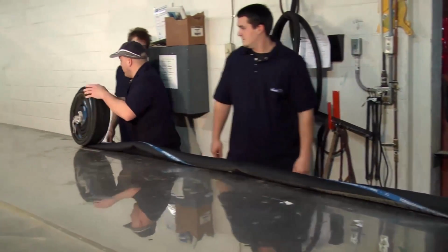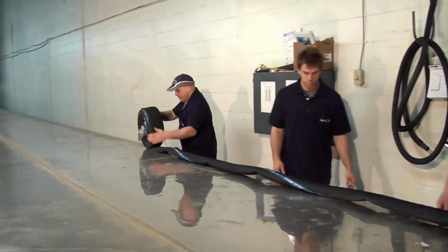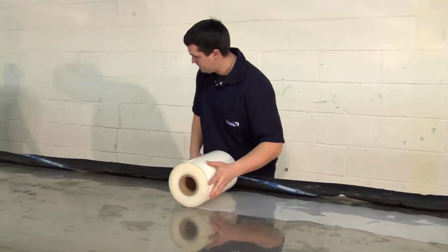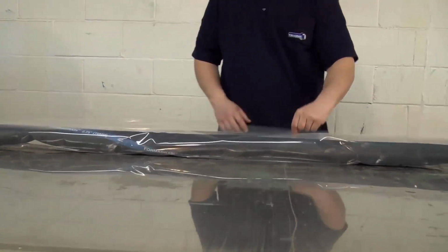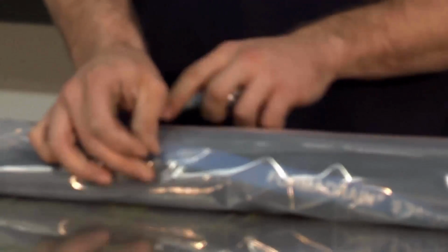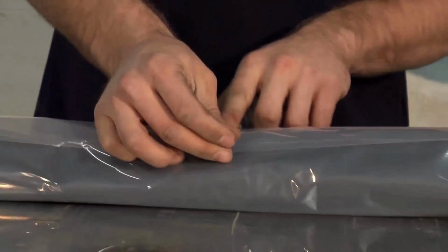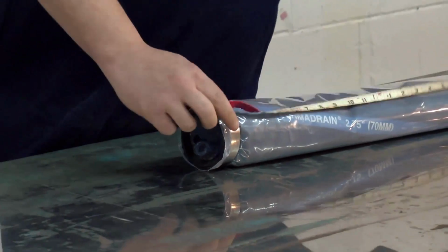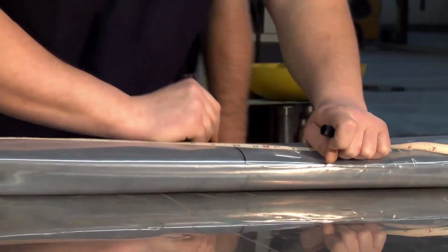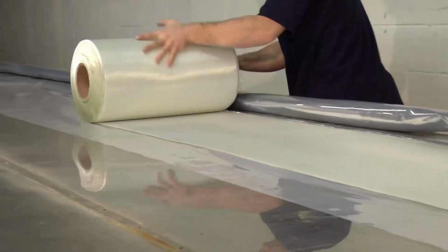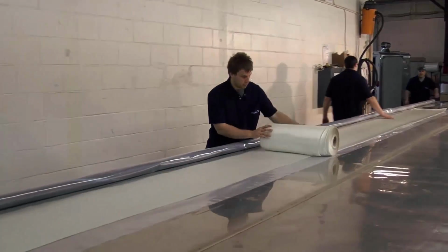It's been steam-cured since '94, so it was designed that way from the start. The preparation starts with laying the bladder down on either a table or on the floor. That bladder is going to be wrapped in a polyethylene layer so that the epoxy doesn't stick to the bladder, because it is reusable. Once that is wrapped, we're going to mark our measurements on the bladder and lay down the fiberglass layer by layer, which is usually a 2-layer repair.